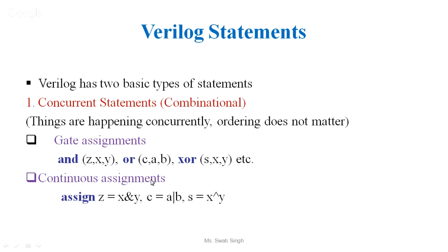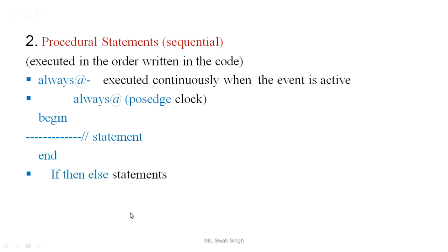In continuous statement, you write the assign operator. Assign, just write z, your output, equal to x and y. So it is better to write this gate statement. You can use continuous statement, use the assign operator and write your statement.